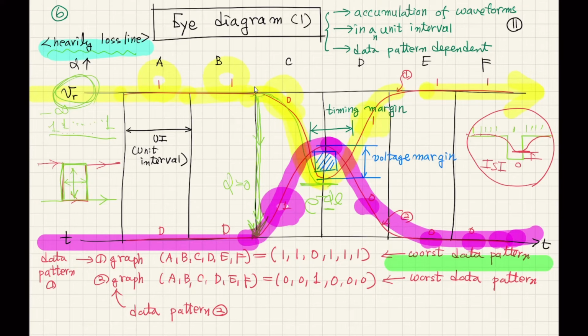But actually, what is happening is here we have only a very, very small window to reduce the power consumption for this high-speed interconnection. Usually, let's assume this is 1 volt level. Now, this is becoming 100 millivolt level to reduce the power consumption. And so this is becoming less than 10 millivolts. And this timing margin is usually in this stage, probably 100 picosecond, which is extremely small.